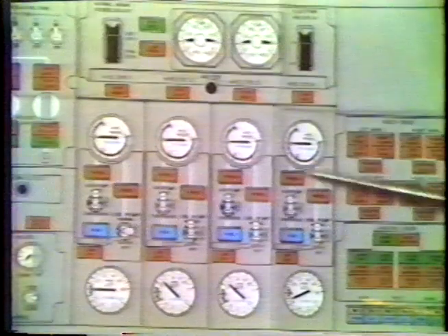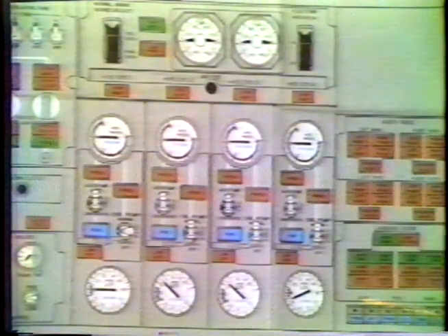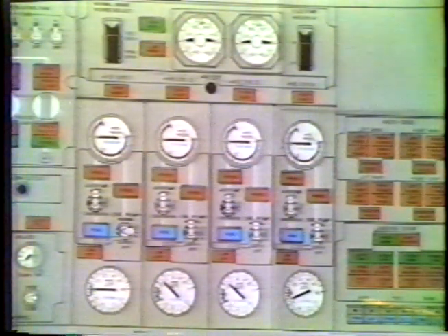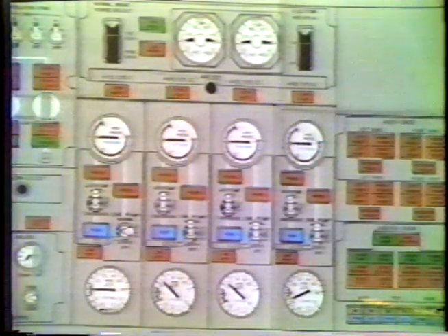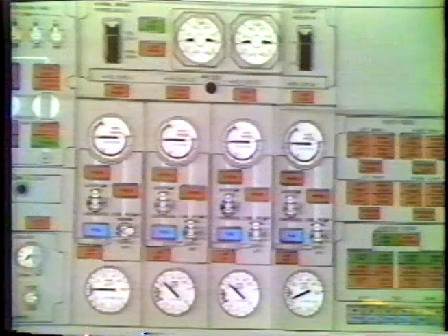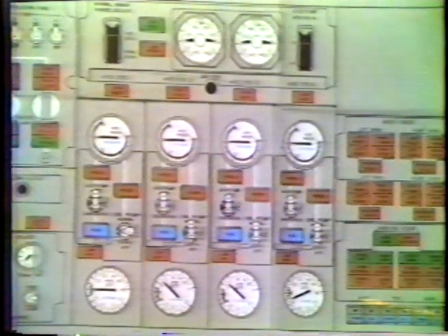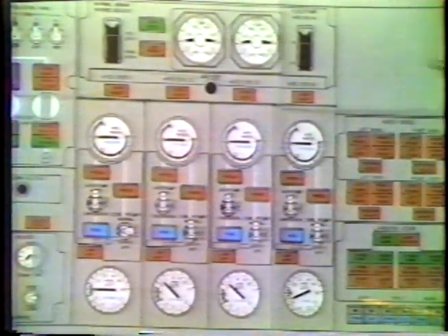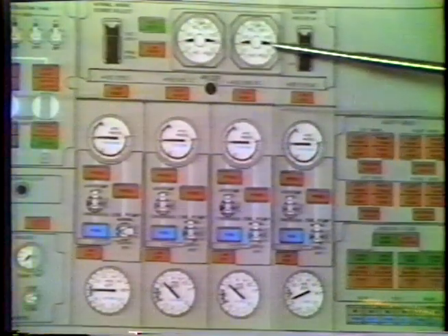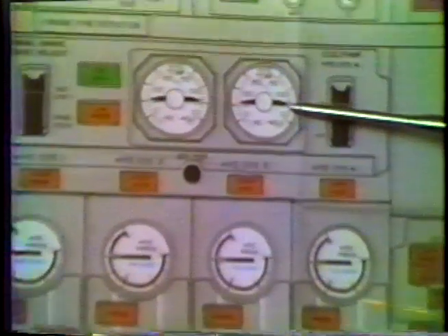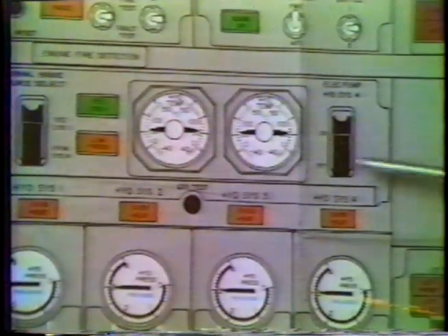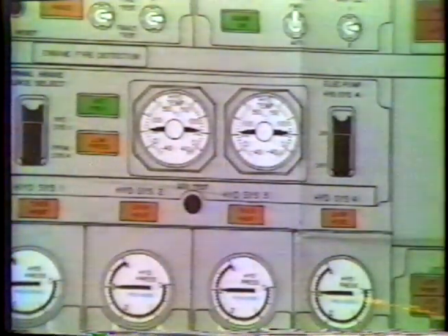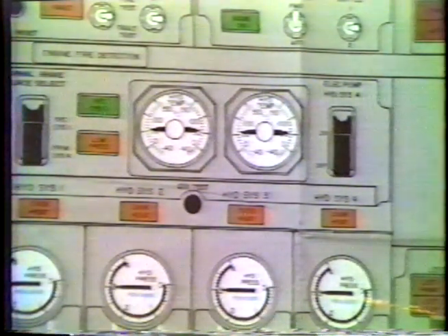However, the system could be depressurized for all except the final phase of flight and pressurized for the approach and landing and written up for maintenance. And of course, if the temperature in system number 4 rises only when the electric pump is operating, that would indicate that that particular pump is faulty.